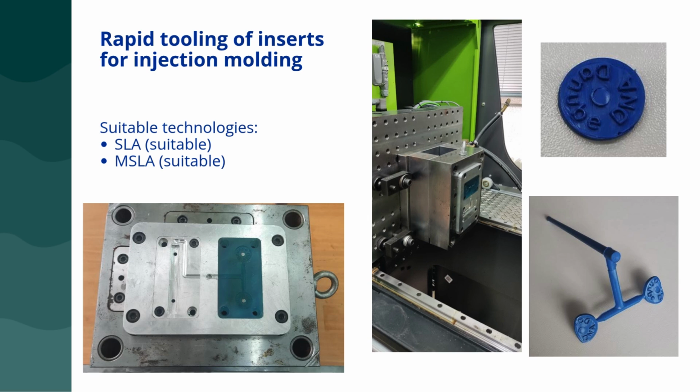As you can see, the final product is not yet fully developed. We will need to perform some fine-tuning to prevent errors related to the ejector. Additionally, the ejecting plate in this die has been produced using FDM technology, and you can see that this die consists of more than 2 parts made through 3D printing.